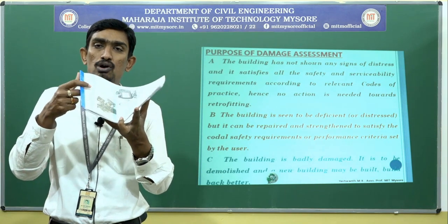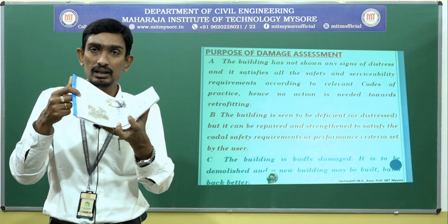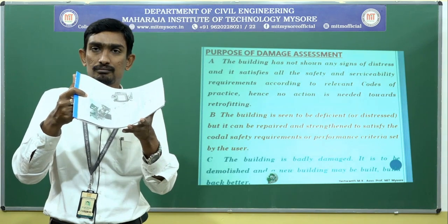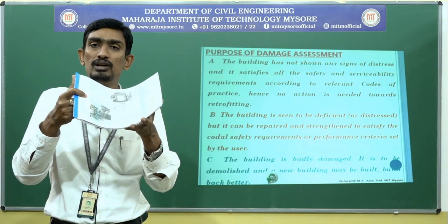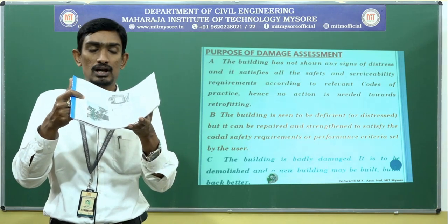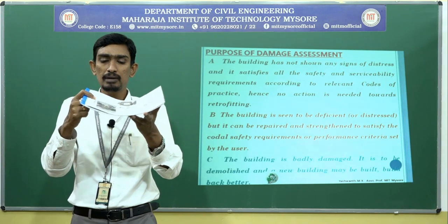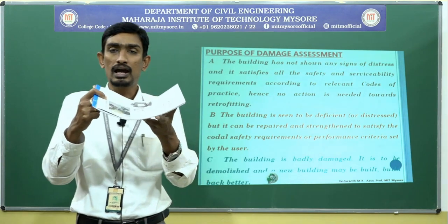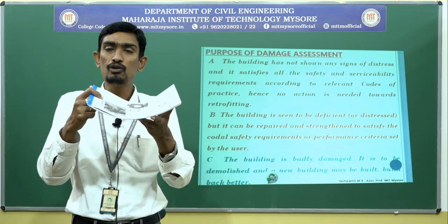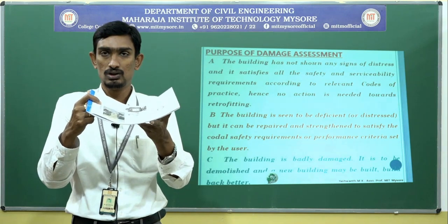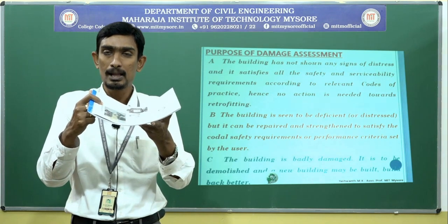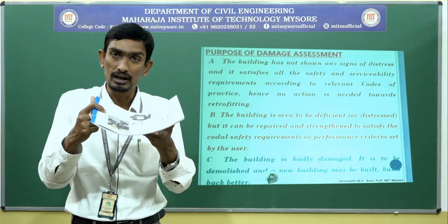The topmost zone, once it undergoes bending, will be in compression, and the bottommost zone will be in tension. So once the beam is going to bend like this, the topmost zone, which will be under compression, will be taken care of by the concrete.